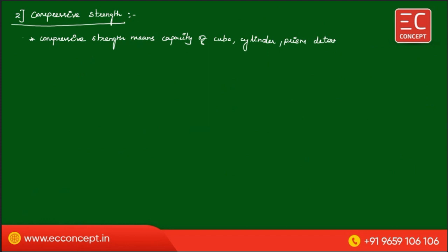determined by applying axial force. So there is a cube. The cube will be tested by applying compressive force. Before failure, from the stress strain curve, you can find out the maximum compressive strength of the cube. Generally this is the compressive strength.